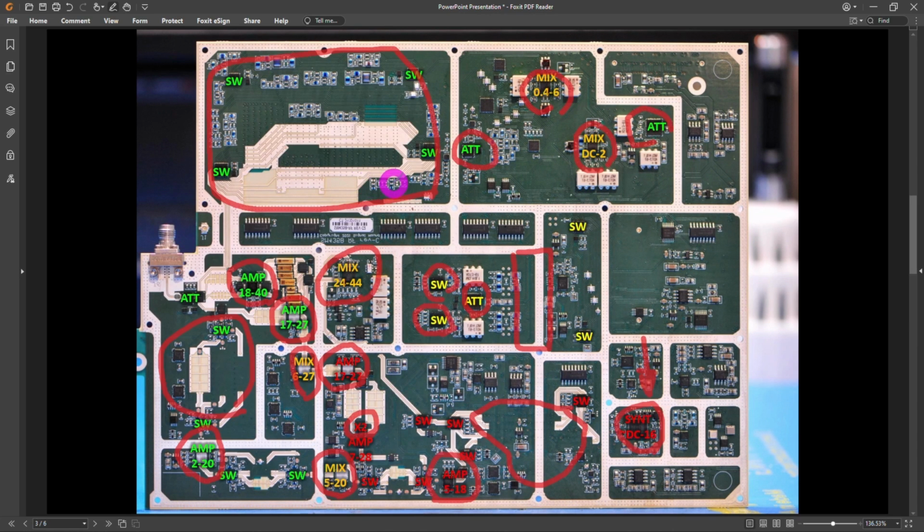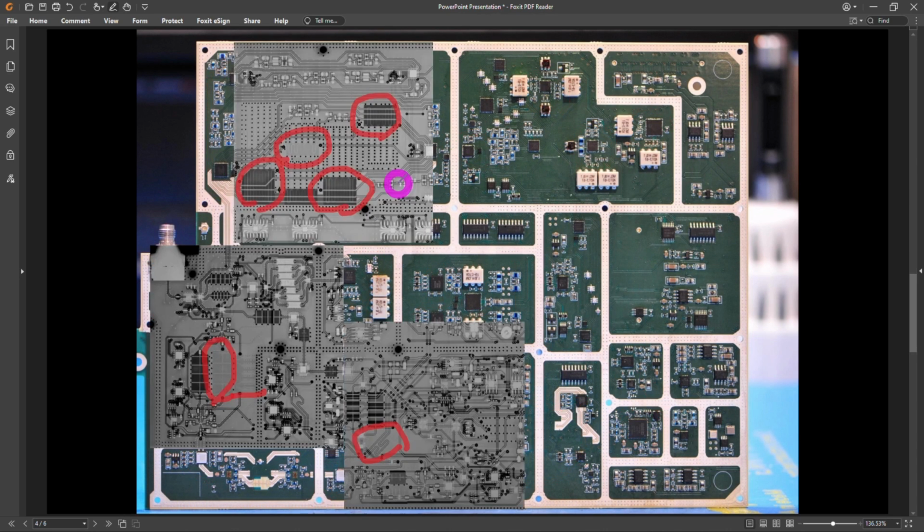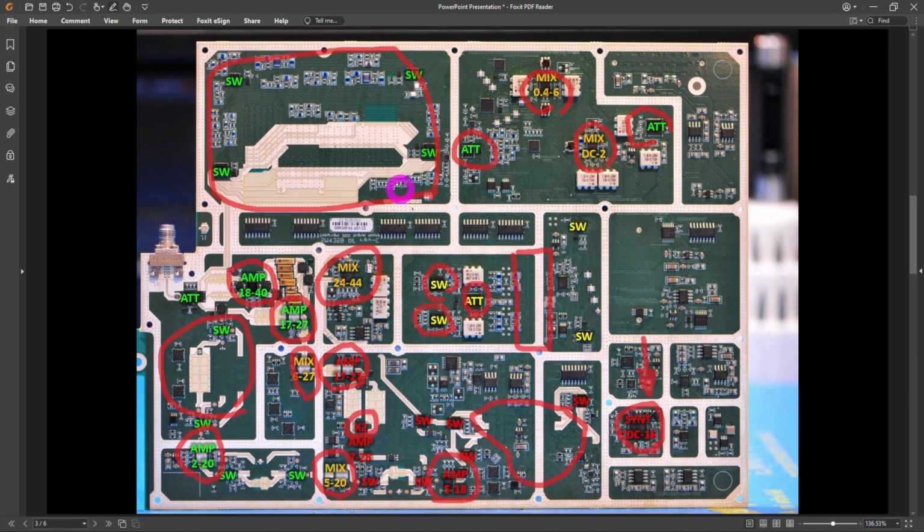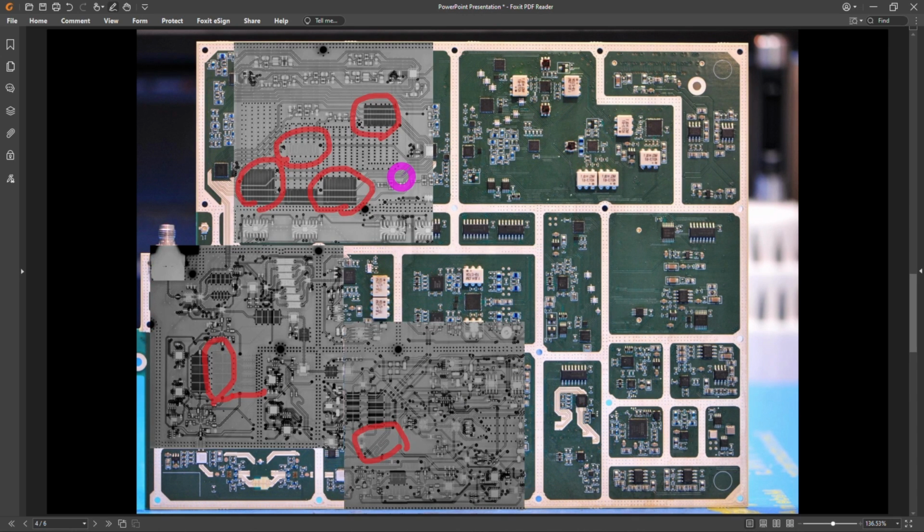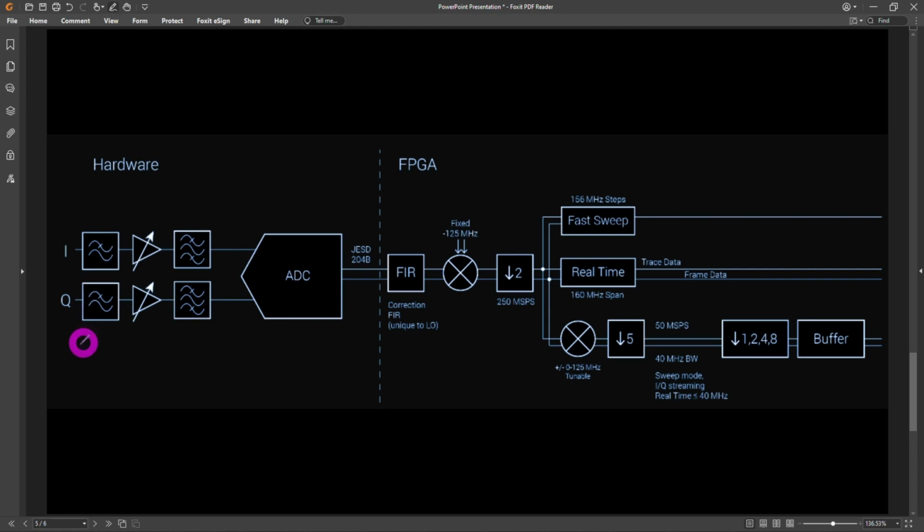But going back and forth shows you the magic of the RF that's hidden even from the sight, by the amount of work that needs to go into it. It's just nuts. I think it's a wonderful design. Now we can take that and think about what do we do with the IF signals. But once you have the IF, especially once you have the I and Q, relatively things become simple, because with very good ADCs that are available, you can actually digitize that right away, go over a JESD interface, and then